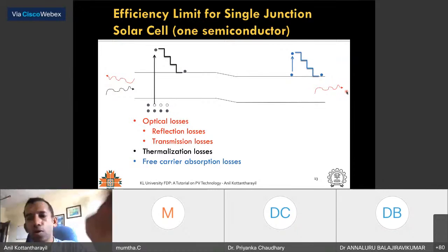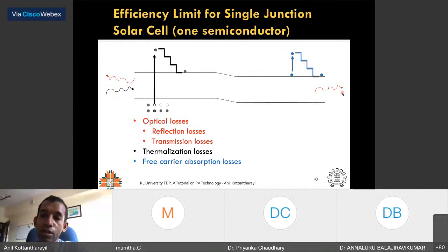The solar cell that we have seen has aluminum on the backside, so this light will be reflected and travel back to the front side. During that time, it can also be absorbed. The path length for this reflected light would be totally 2 times the thickness of the silicon wafer.